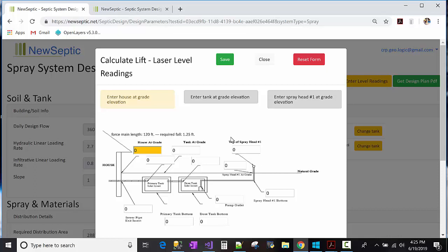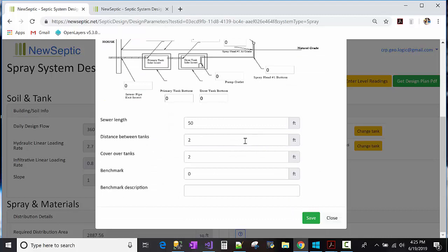I've had contractors say that you really only need it as far as surface water drains or different criteria other than the 1% rule. But NewSeptic calculates it on 1% based on the fact that this is a wastewater system and there might be some particulates in it, and having a 1% slope back would be a good idea.